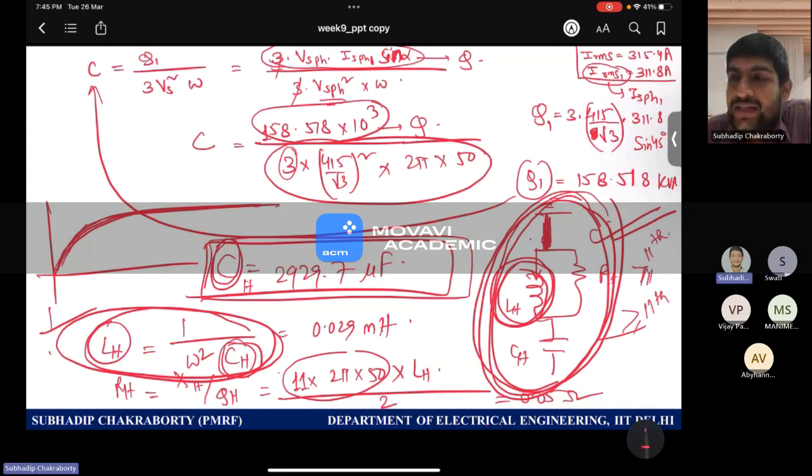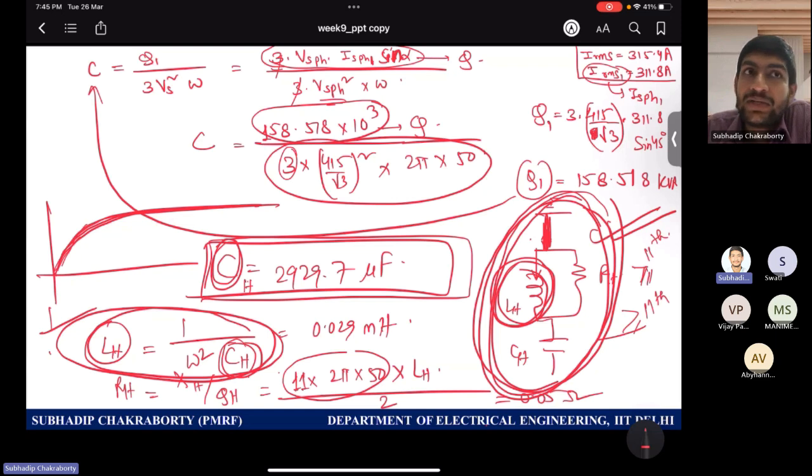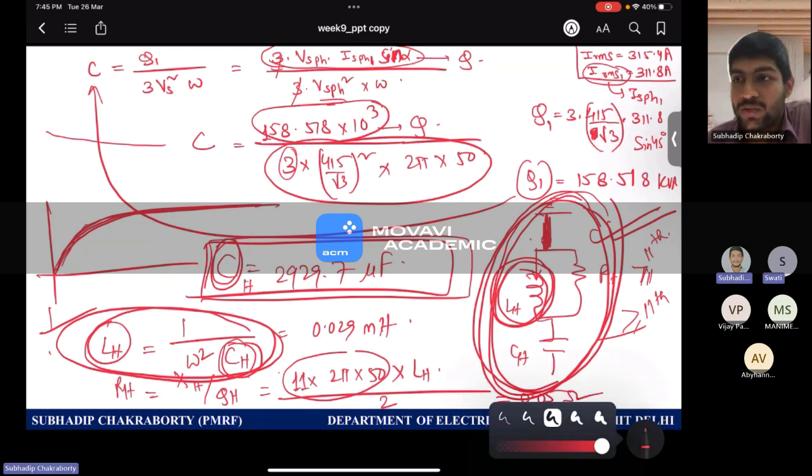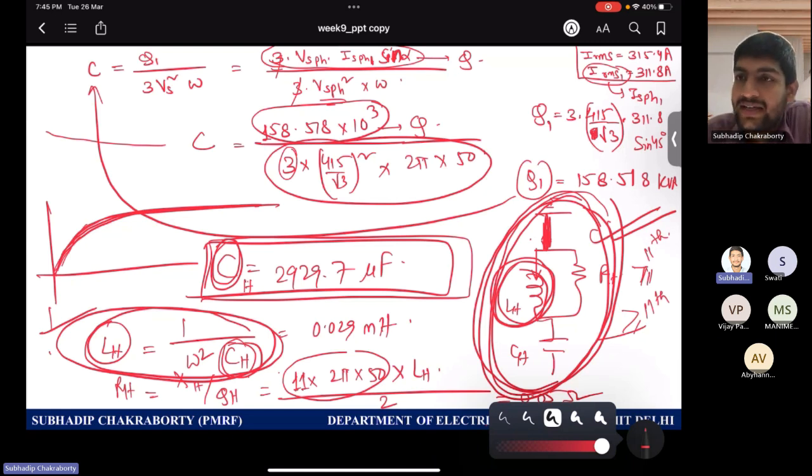Obviously, we are doing numericals, but in practical situations, we do some analysis on what kind of load current harmonics it can bear, and what we want to attenuate from the supply. Also, when we go to much higher order harmonics, their amplitude reduces, so maybe a high pass will do. But if it is too distorted and you want to provide harmonic compensation by providing a low impedance path, then it is okay to provide a dedicated single tuned arrangement in a sub branch, like we calculated for the previous problem.